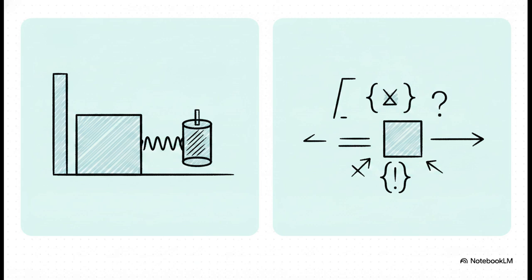A physical model represents the actual physical components we want to study. For instance, we might decide a system has basically zero damping, so our physical model is just pure masses and springs. A mathematical model, on the other hand, takes those physical elements and defines their input-output relations using simplified equations.